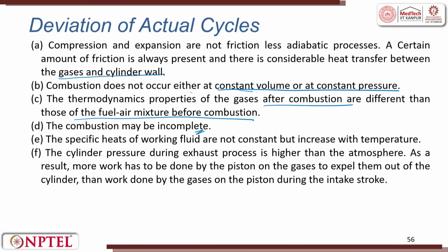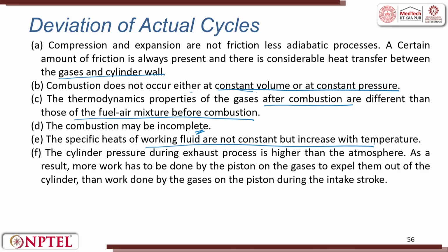The combustion may be incomplete. Not all the diesel particles or the air particles get burnt. Once they do not get burnt, it again brings residue and other things. The specific heat of the working fluid is never constant. It increases with temperature. How much does it increase? What is the exponential increase? Very hard to find out.